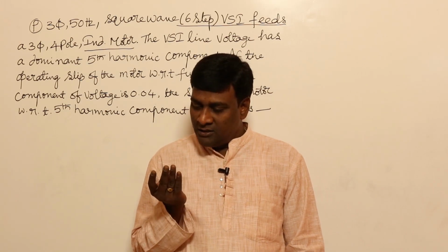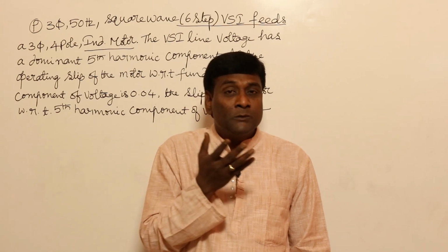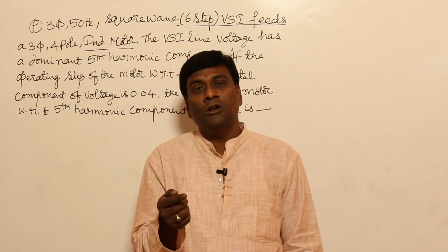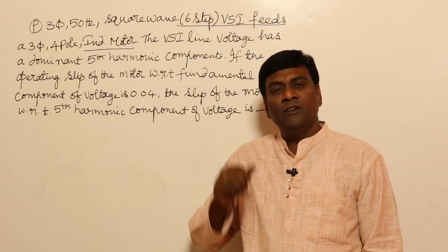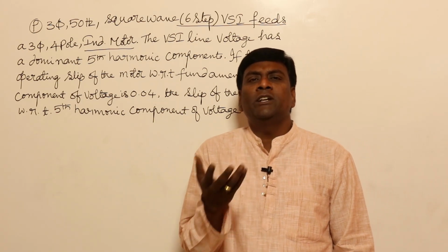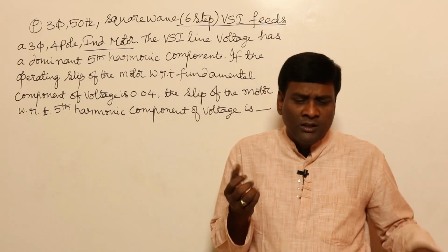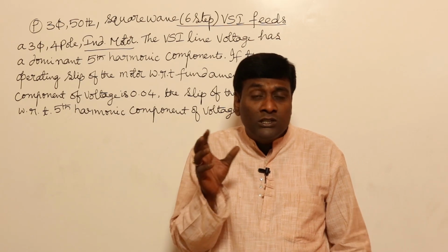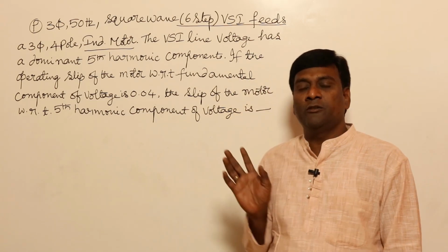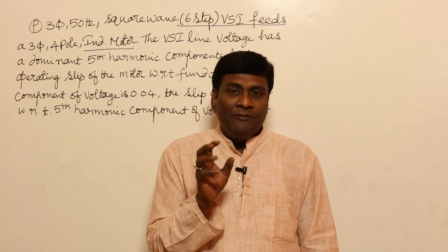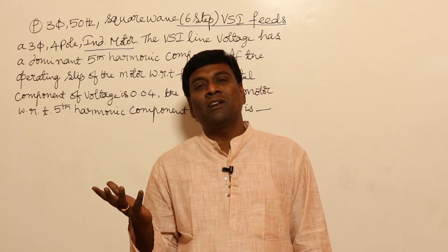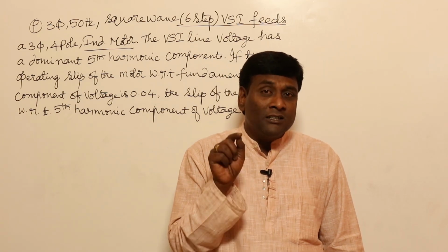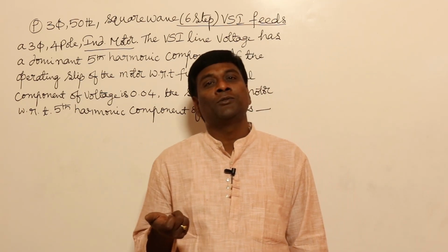But in the induction motor, we should not assume that. Why? Because in practice the input voltage of an induction motor may not be sinusoid. For example, in V/F control, how do we control the speed of an induction motor? Because the induction motor is everywhere, most induction motors are controlled by power electronic equipment. So the practical existence of power electronic equipment is more along with the induction motor, and the input voltage may not be sinusoid.